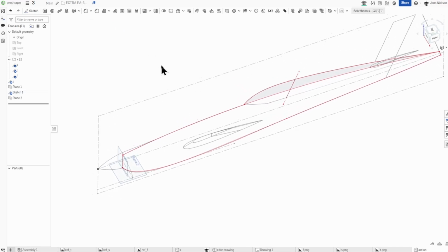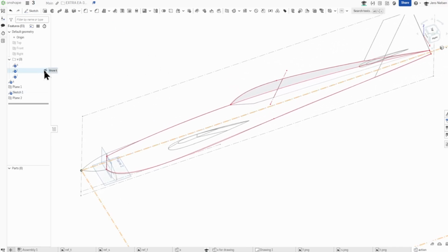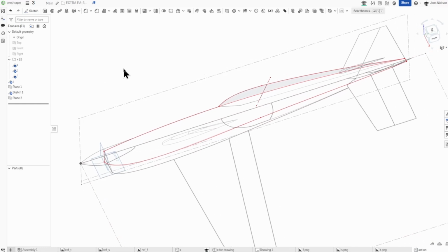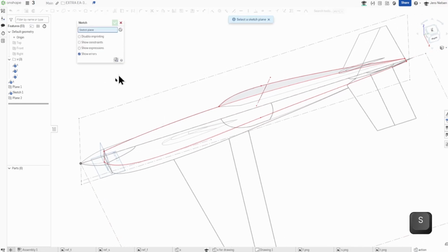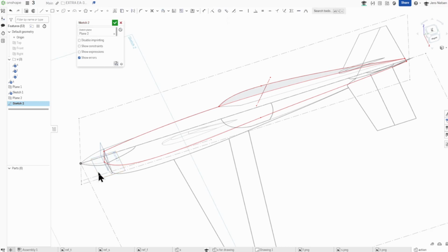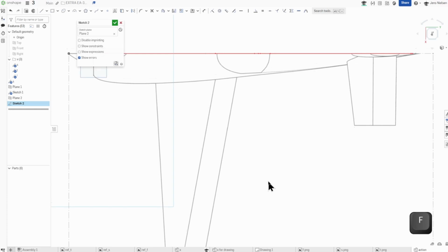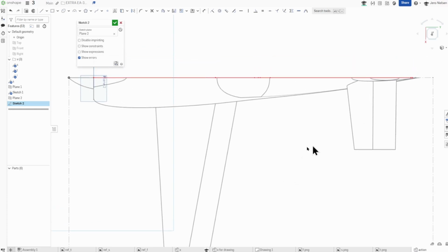Okay, plane is defined, right? Edge of sketch 1, yeah, there it is. And now I'll make that top plane visible and draw a sketch on that plane, which will connect these profiles. So that'll be one spline from here to there.